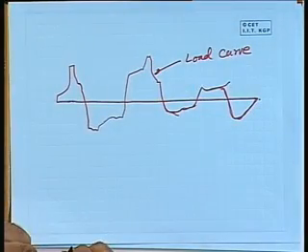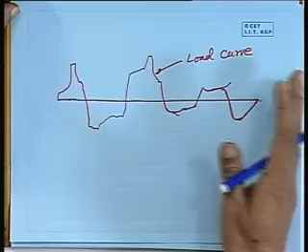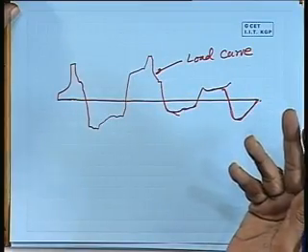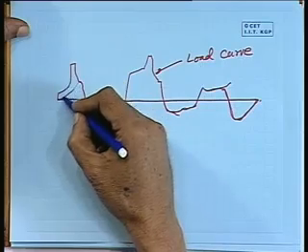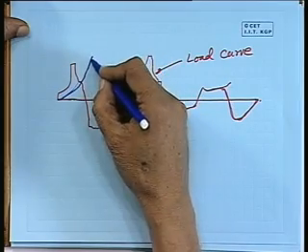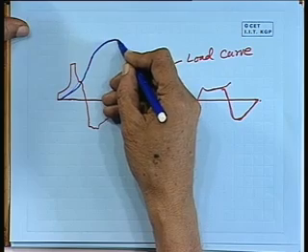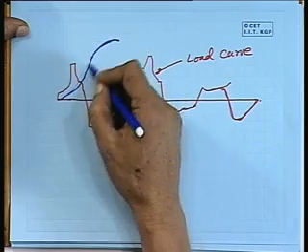Okay. So under this condition, we take one of them and we say that this is the load curve. Now we go back to our basics, and if you integrate this load along the length, then we get what is known as the shear force curve. So if you try to integrate it, how it will go is something like this. It will keep on increasing, then there is a point of inflection, and then the rate of increase will decrease.